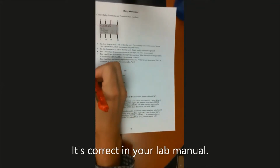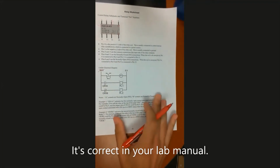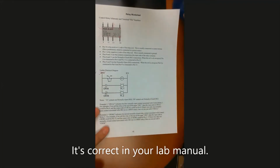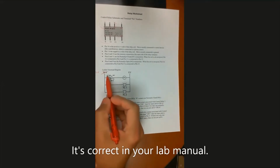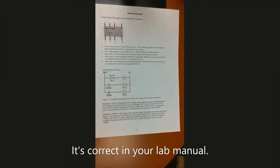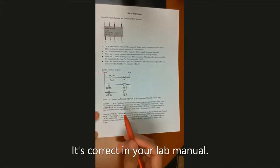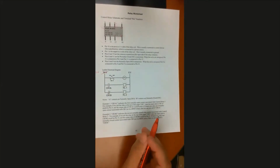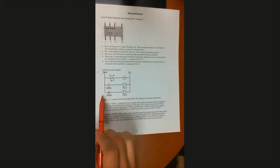That's going to have to be 12 volts. Just the way that TinkerCAD has their components set up, that's going to have to be 12 volts. If it's 24 volts, then you can play around with it, but it's going to show that things explode in TinkerCAD. So to make everything work out all right, just change that to 12 volts, and that'll be totally fine. Okay, so just think about what's going to happen in this circuit.